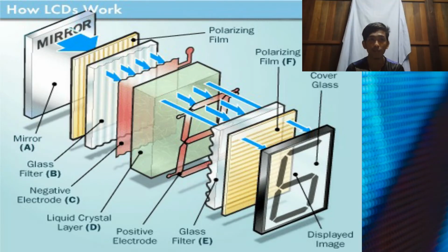Okay, I will explain thoroughly about the working principle of the LCD display. The main principle is that liquid crystal molecules tend to untwist when electric current is applied to them. This causes a change in the angle of the light passing through them, and a change in its angle with respect to the top polarizing filter. So little light is allowed to pass through that particular area of the LCD, thus that area becomes darker compared to others.